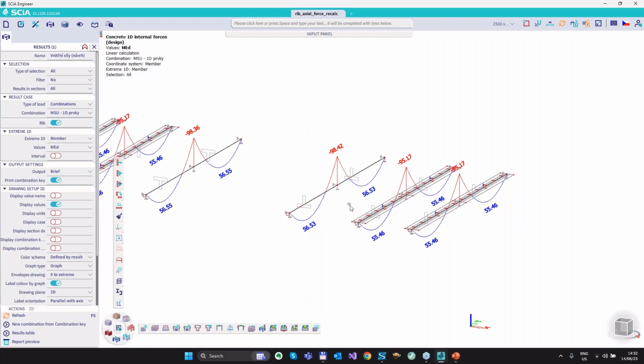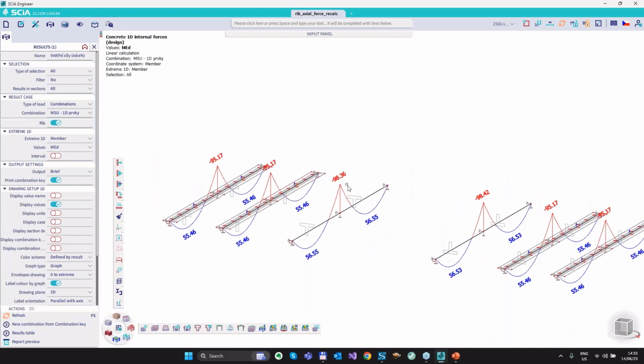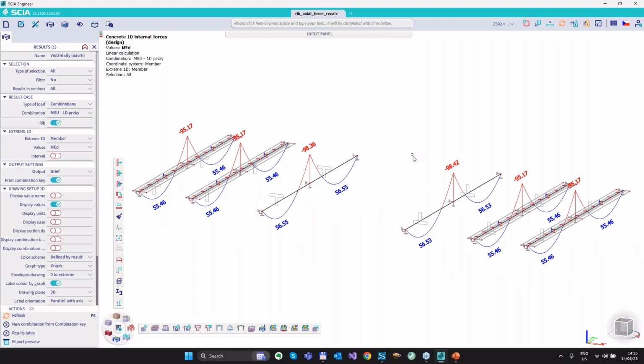It's important that, as I said, now the recalculation is done for any axial load, so it doesn't matter whether positive or negative, just to have transparent results when you compare the results, for instance, with this simplified T-beam, because of course there can be a discussion whether increasing the moment above the support, for instance in this case, is necessary or not. But to have a really fully transparent solution, we decided to make it this way.